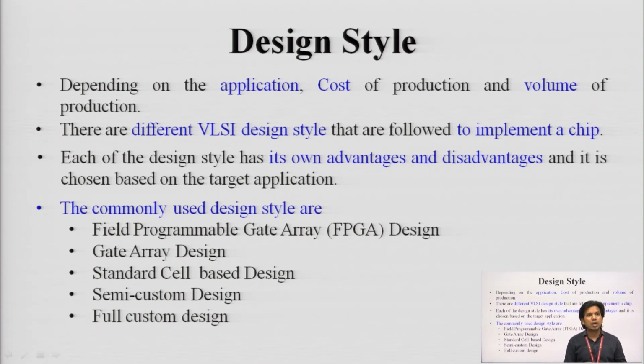The first one is the field programmable gate array design, clear, the second one is gate array design, the third one is standard cell based design, the next is semi custom design, and the final is full custom design. So, these are the different techniques which you can adopt based on the application, the cost of production and the volume of production, clear. It is up to you what kind of output you require, and based on that we can adopt any one of the design techniques. We will see all of them one by one. First, we will see field programmable gate array design.